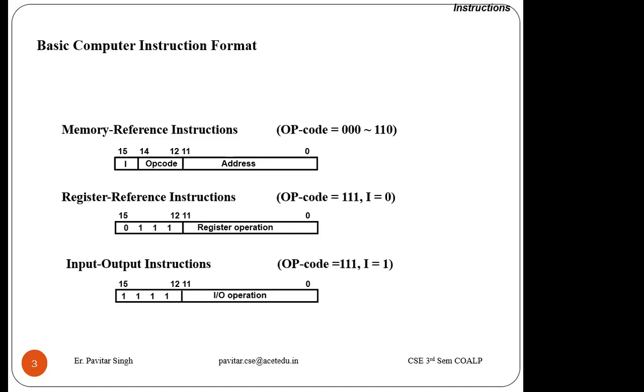As your memory has a capacity of 4096 times 16, from this your instruction size is 16 bits. This is your instruction size or data bus size. And 4096 you can write as 2 raised to power 12. So from here you can calculate the size of your address.